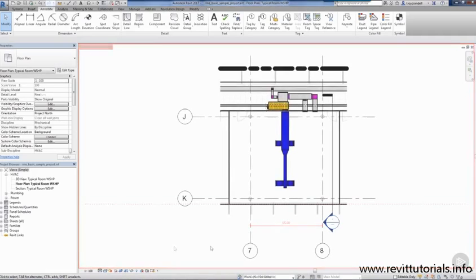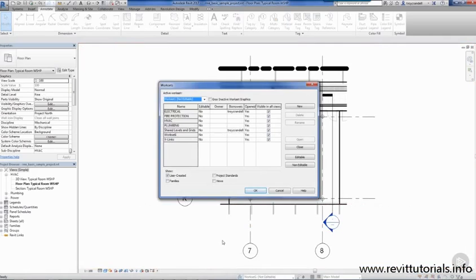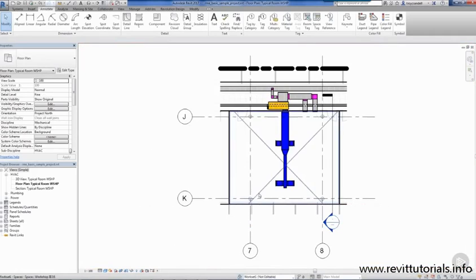We've discussed work sets a little, and you'll hear more about them as the course progresses. This is the work sets dialog where you manage the work sets. Elements are placed on the active work set, which is displayed here. Clicking the arrow here allows you to switch between all the work sets.